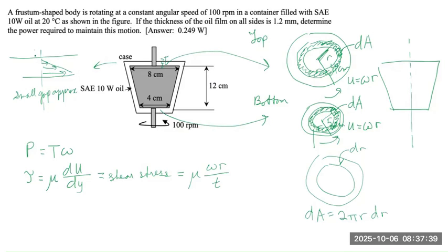And over here we have a thickness of T. This portion is basically this portion over here, but zoomed in. And why it is T is because the largest gradient occurs at the boundaries, so that's why we use the height of T, because we have the largest change in velocity. We have maximum velocity at the frustum surface and zero velocity at the top.